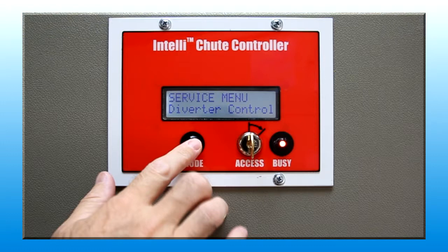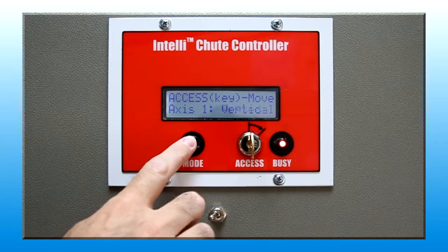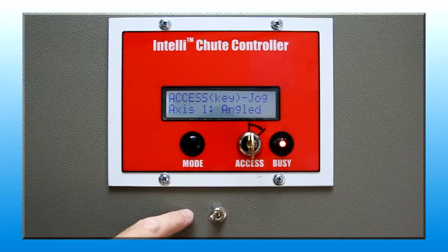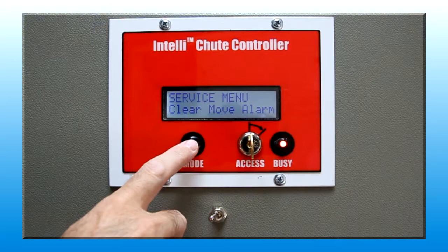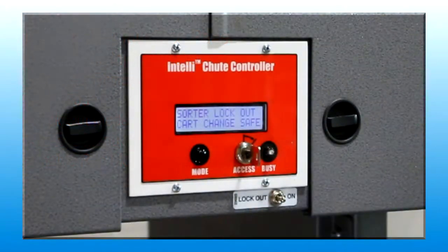To select a sub-menu item, turn the access key. Press the mode button to navigate through the sub-menu item list. An end of section marker also follows the last sub-menu item, and pressing the mode button returns back up to the beginning of the main service menu. After completing operations requiring Chute locked out service mode, set the toggle switch back to the enabled position to restore normal intake door access.